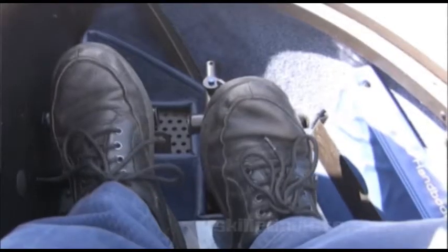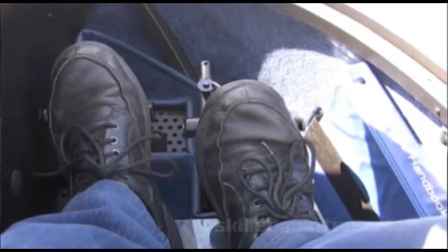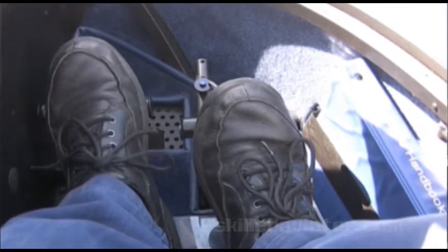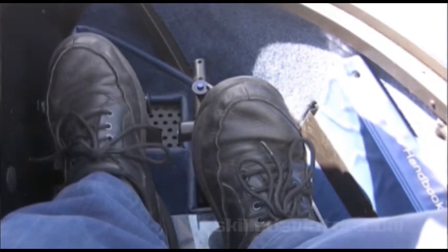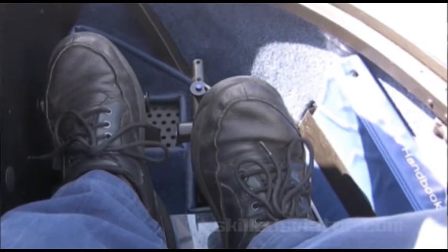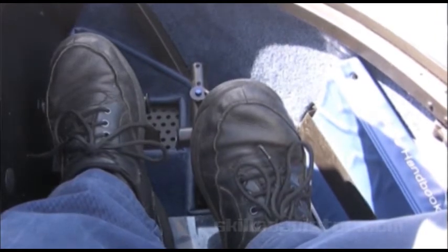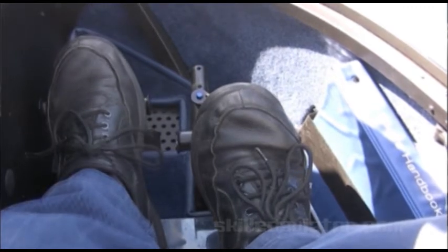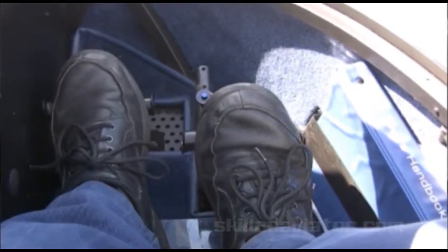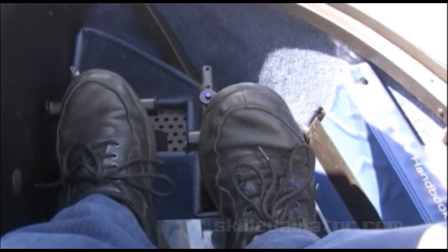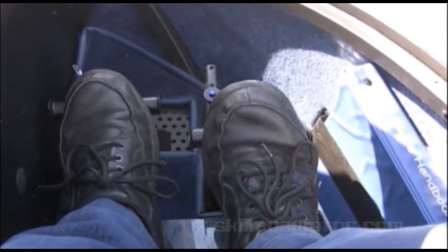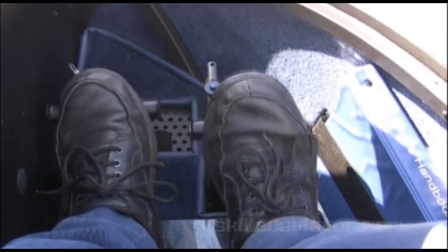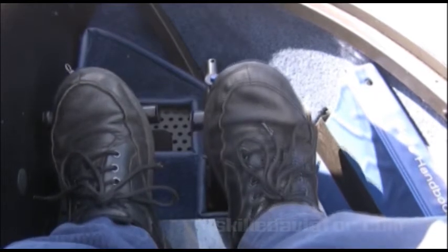And when the helicopter is in a hover, a little left pedal is required to counteract the torque of the main rotor. If the pilot wanted to turn to the left, he would increase the amount of left pedal, which would increase the thrust, resulting in a left turn. If he wanted to turn to the right, he would decrease the amount of left pedal, which would reduce the amount of thrust, resulting in a natural torque reaction, turning the helicopter to the right.